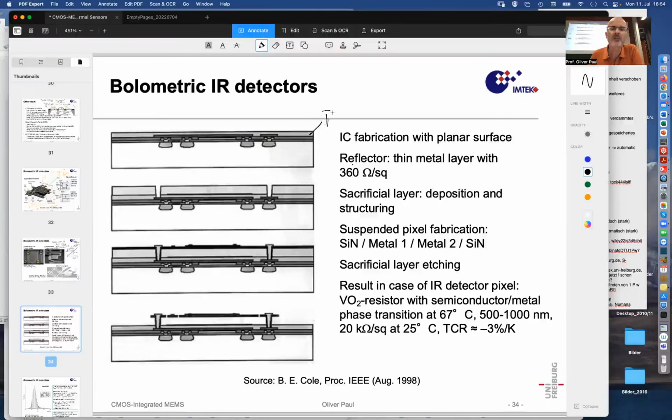The passivation layer is also opened to reach some contact pad to some subjacent circuitry or subjacent metal lines. And then there is a thin silicon nitride that is deposited by chemical vapor deposition all over the place and into these little holes.